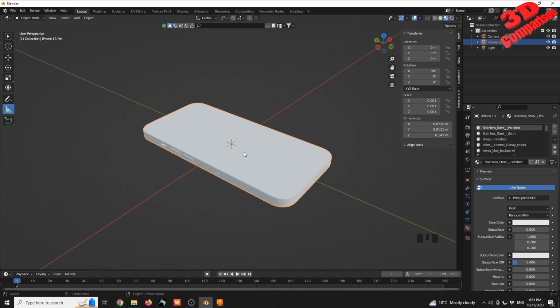It's the same problem with KeyShot. You can add the decals on the model, they will look great within the software, but when you export them to something universal like OBJ or FBX, they will not have UV mapping. So this is why if you model this in Blender, afterwards you can take it maybe to a website, to Unity, to a VR environment, and so on.